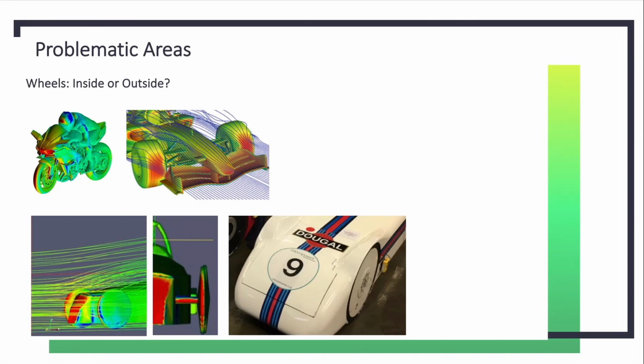The other thing that you'll notice on the CFD images now, and I'm hoping that you're starting to keep up with me, is that we actually have a little bit of separation here, and that's the blue region. The reason for that is actually to do with the coverings on this particular wheel and the fact that they bow outwards, a little bit like a triangle like that. That isn't great for airflow, and in fact you want them to be as flat as possible.